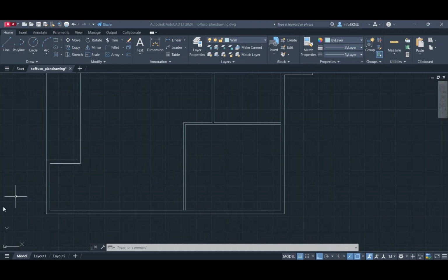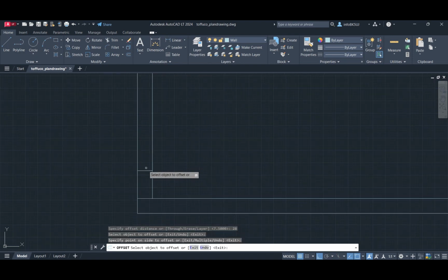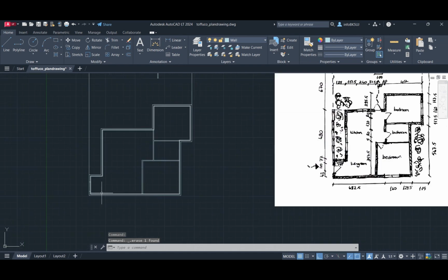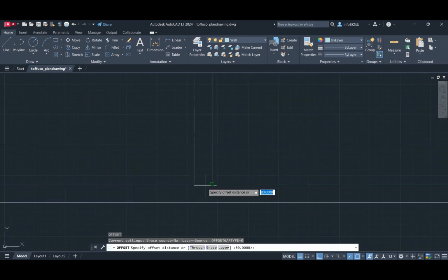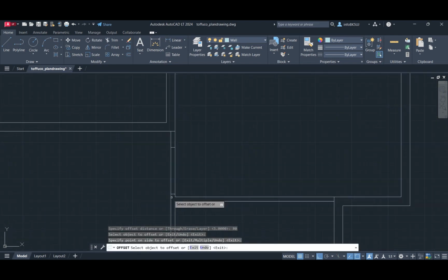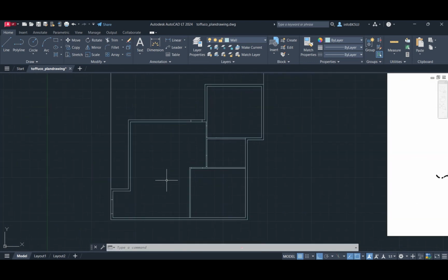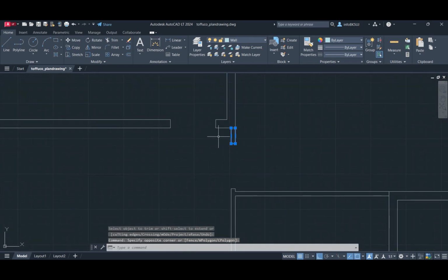After the wall drawing is finished, we can draw doors. We determine the places where the doors will come, and we open the gaps with the Trim command. After trimming, we join the lines to make them continuous lines.